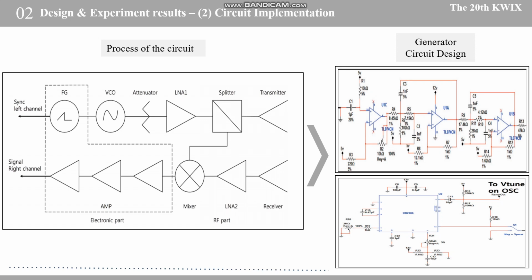And the other part is the RF amplification of the transmitter. Mainly a power amp is used, but the radar system in the current project uses an LNA that has a high gain but produces a small output, because it is too risky to use a high power device for research and experimentation.